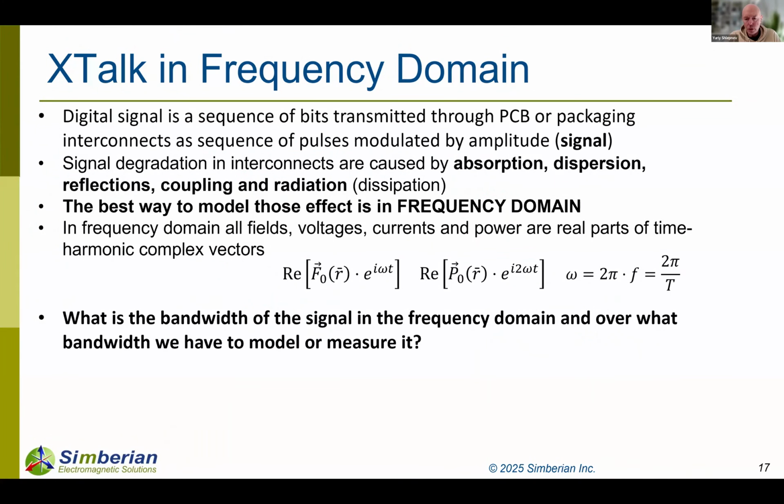Those adjustments are important if you need to see actual impedance or even actual crosstalk. A small variation in width may give you a large variation in crosstalk, and that's important to have.